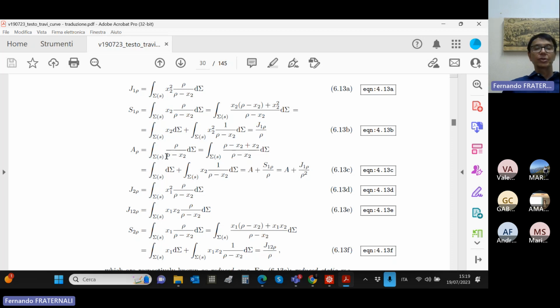If the curvature, which is the reciprocal of rho, is near 0, it means that rho is approaching infinity. So for beams with a moderately large curvature, this J is approximately equal to 1. But for beams with a strong curvature, this J is not equal to 1. We will see some examples later.